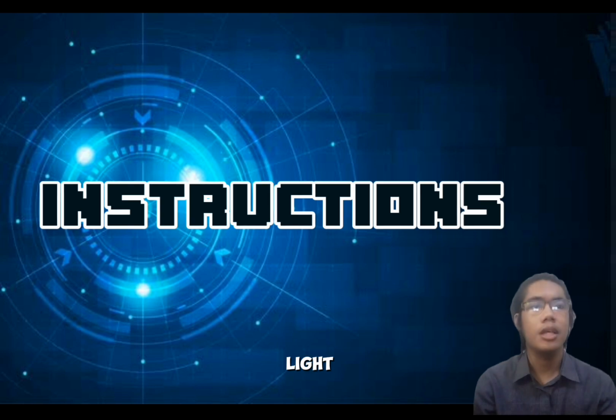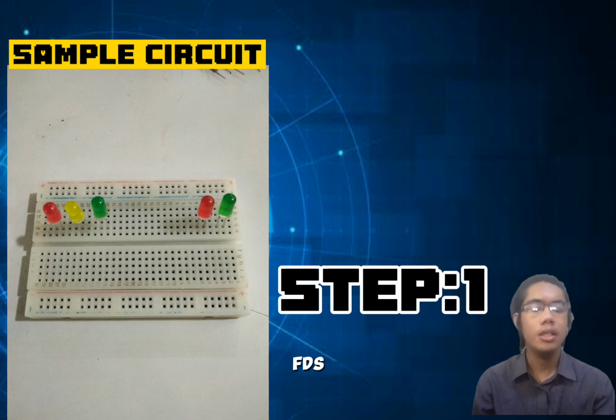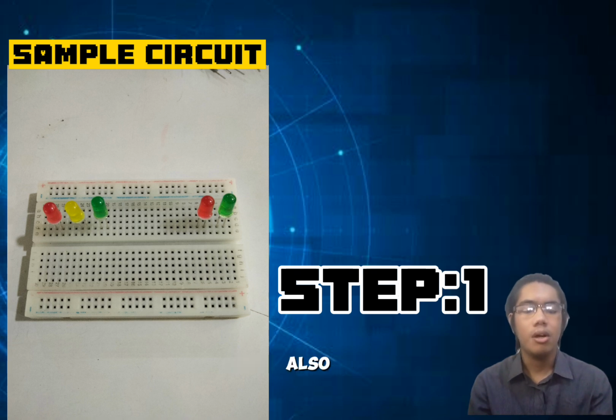Instruction for traffic light Arduino Project 3. Step 1. Place all LEDs on the breadboard. Number 1. Place the car red LED on D27 to D28. Place the car yellow LED on D23 to D24. Place the car green LED on D20 to D21. And place the pedestrian red LED on D5 to D6. Also the pedestrian green LED on D2 to D3.